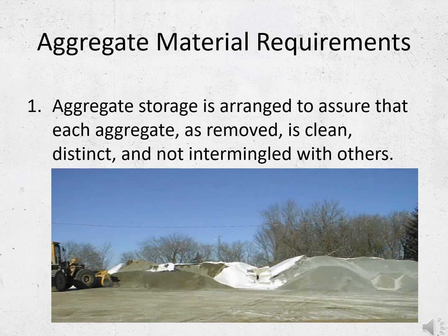Aggregate storage piles or bins should be configured to prevent any cross-contamination and should ensure that the materials remain clean by using tarps weighted down to prevent fugitive dust from entering them, especially fines that can coat aggregates and prevent the development of good aggregate paste bonds. Tour the piles to see if there are any of these types of issues and note any as nonconformances in your audit report.